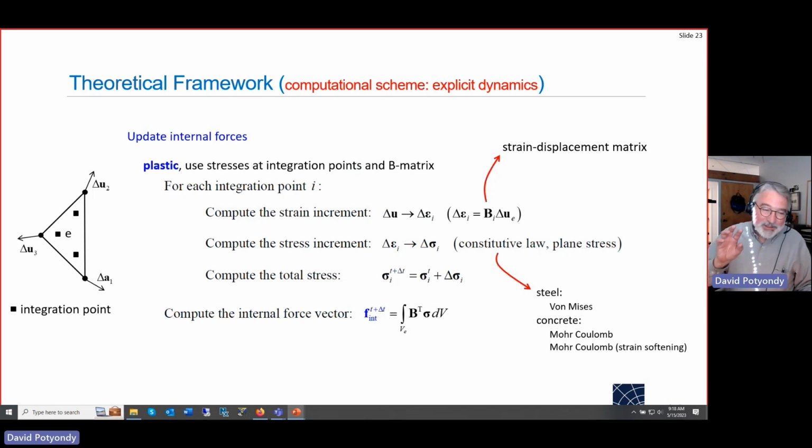These are the same constitutive models of those names that are in the basic FLAC3D for the zones. The only difference is these are slightly reformulated to give the relationships for a plane stress system for the shells, and a similar type of thing for the beams.